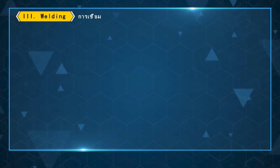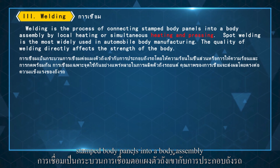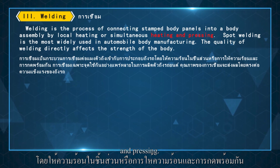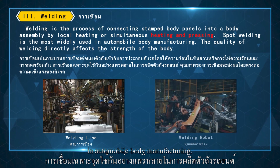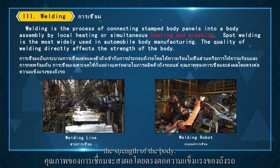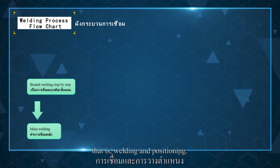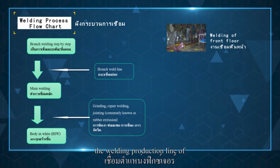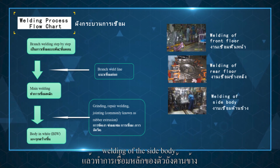3. Welding. Welding is the process of connecting stamped body panels into a body assembly by local heating or simultaneous heating and pressing. Spot welding is the most widely used in automobile body manufacturing. The quality of welding directly affects the strength of the body. The welding process consists of 2 processes, that is, welding and positioning. It is to perform branch welding step by step on the welding production line of the positioning fixture, and then carry out the main welding of the side body.